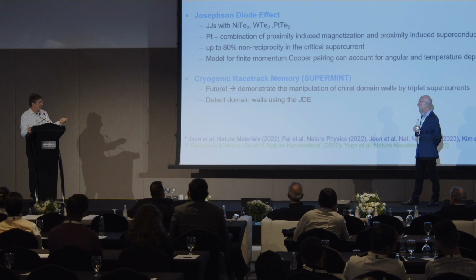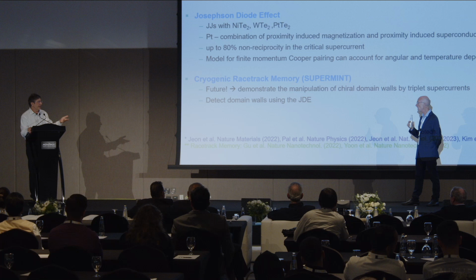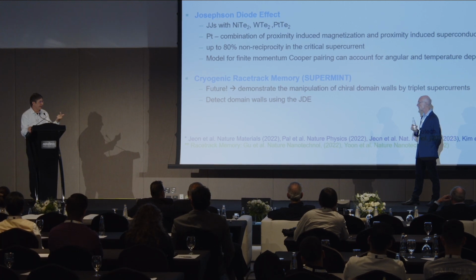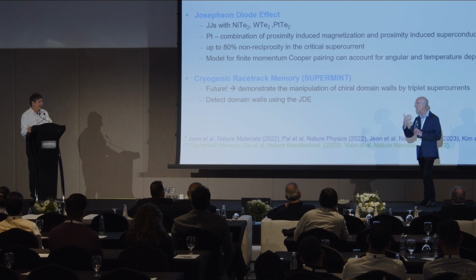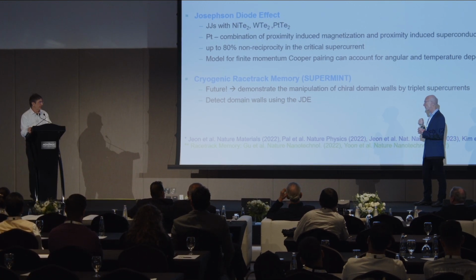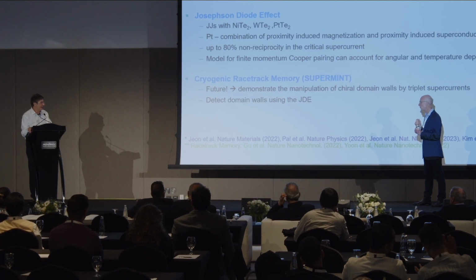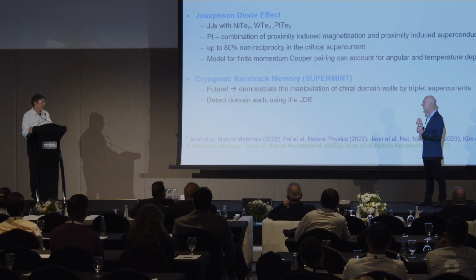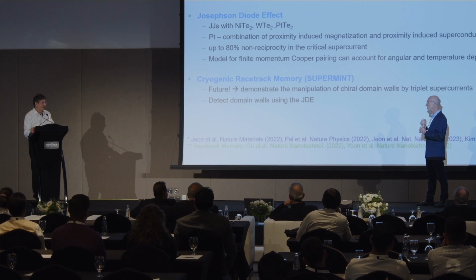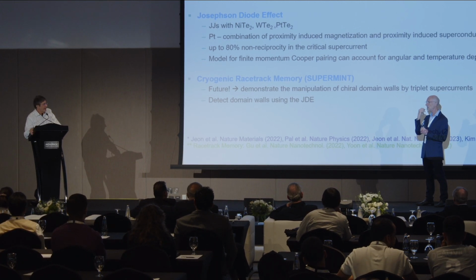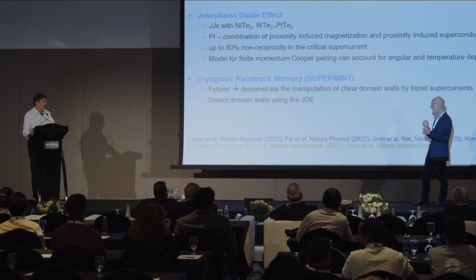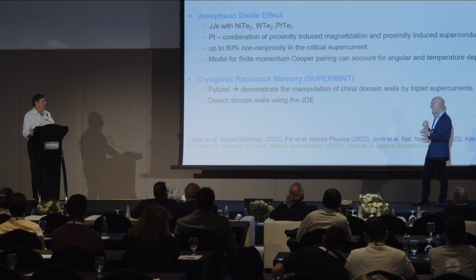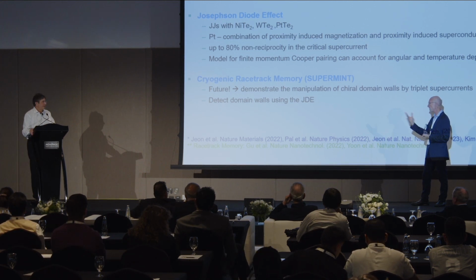You're saying that speed is quicker than rotation of the disk, and energy of mechanical rotation is very high? So much less energy. You don't need to rotate a mechanical object to read 1 bit. But joule losses in your system are probably also non-negligible. They're negligible. It turns out in all memory systems today, most of the energy is consumed in capacitive charging of wires. This has been true for 10 years. So the actual amount of joule energy we consume will be very little compared to these other energies.